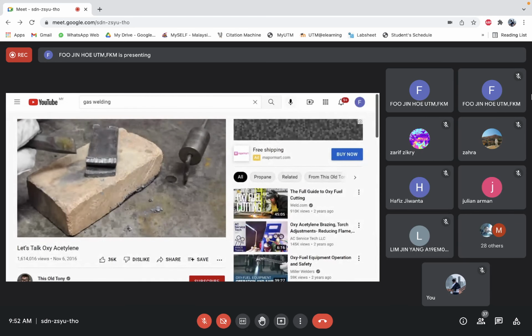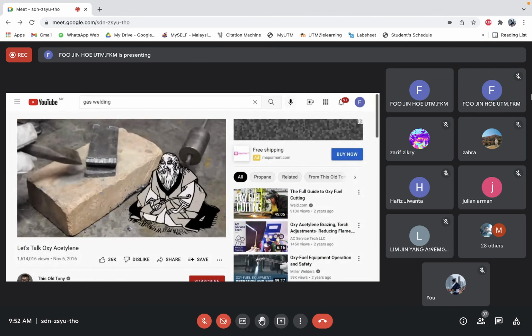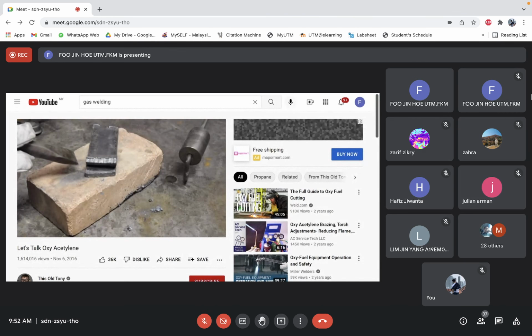Here's a little interesting tidbit. Once that steel starts cutting, once it's started to melt, you technically don't need the acetylene anymore. I remember my instructor was particularly fond of doing that demonstration. As he was cutting, he'd cut the acetylene and finish the cut with just the oxygen. Basically, once the material gets to that auto ignition temperature, the temperature where it would just spontaneously burn, as long as you feed it enough oxygen, it'll keep burning on its own. When you make a cut with an Oxy Acetylene torch, you're basically making it rust very, very fast until it breaks apart in 2 pieces.